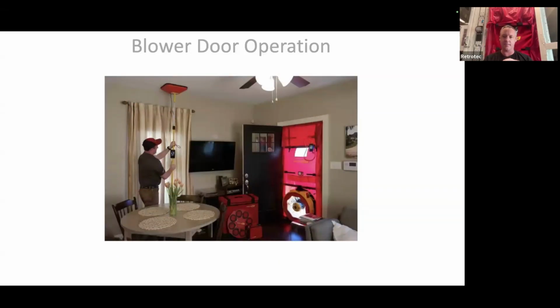It's a pretty simple device. It's just a plastic pan with weather stripping around the edge, with a port where you can plug in a tube, just like on your manometer or on a fan. And then there's also a spot to screw it into an extension pole, like a painter would use. That way you can kind of reach up into high ceilings and stuff like that.